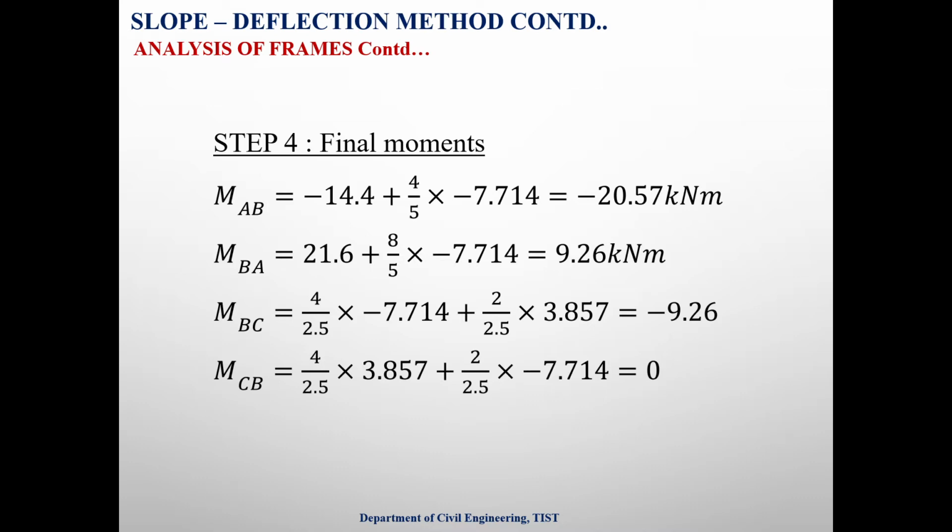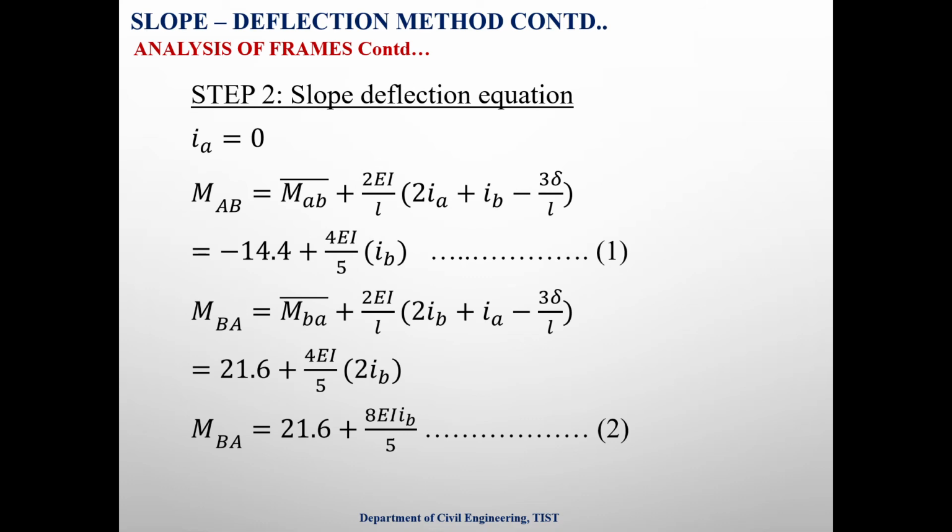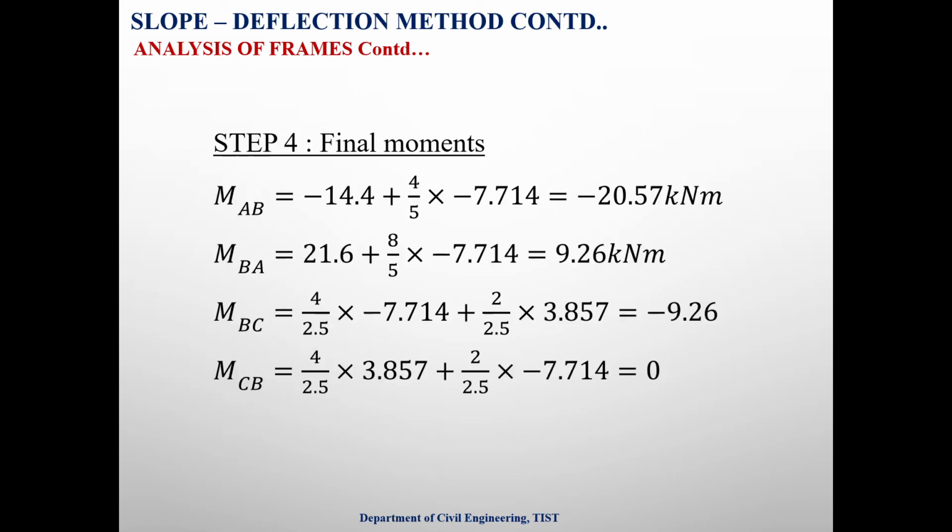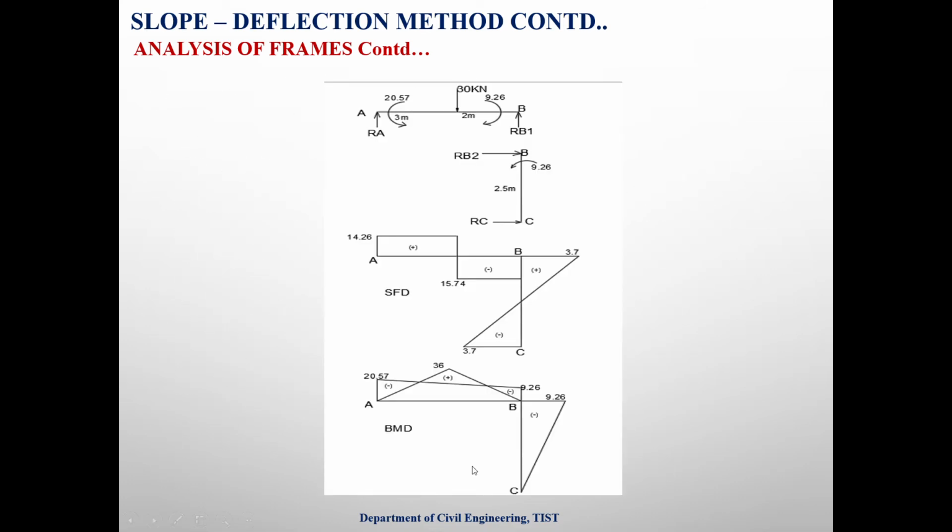After getting the final moments, draw the bending moment diagram. Firstly, draw the free bending moment diagram.